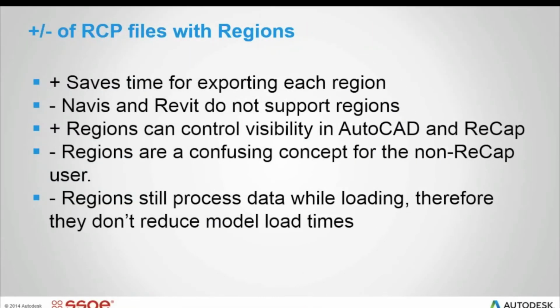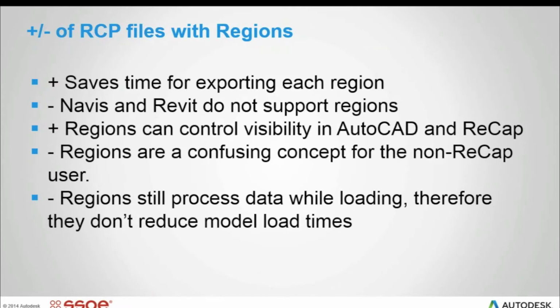So when it comes to doing point clouds, the pluses and minuses of RCP files when you're referencing directly into your CAD software. If you're working with small files, let's call it 2 or 3 gig raw data, or maybe you did an electrical substation or something like that, and you only had like 10 or 15 shots out there, you don't really need to go through the process of chopping stuff up. Yeah, it's nice, it's convenient, but the data is so small, it's not a big deal unless you're trying to get that 2D print set. So the RCP file, in that case, saves time for exporting, because you don't have to do one for each region. You just create your regions directly in the RCP.